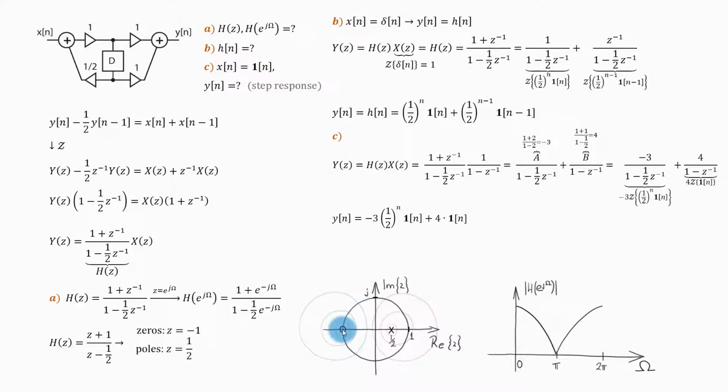And this point corresponds to the normalized frequency equal to pi. And I continue. I go up the valley, up the valley, up the hill, and I will come back where I started. So when I trace the magnitude of the transfer function above this unit circle, I will get this. So this is an approximate sketch of the amplitude frequency characteristic of my system.